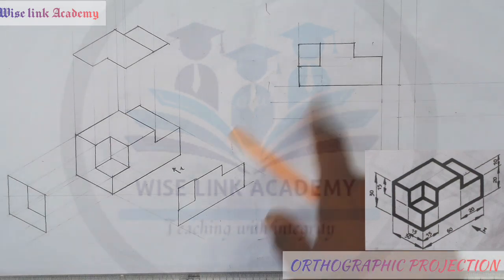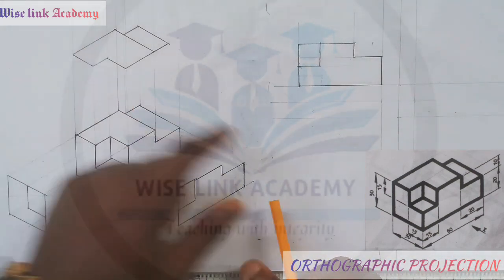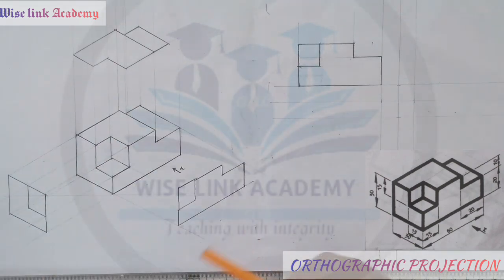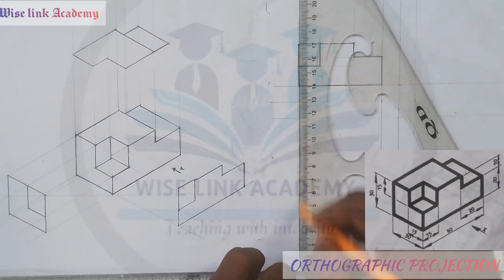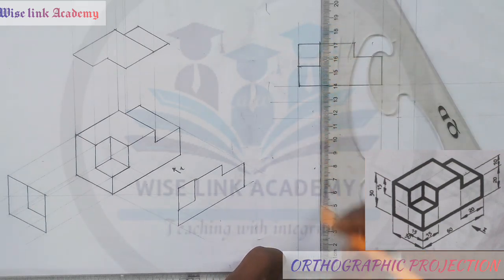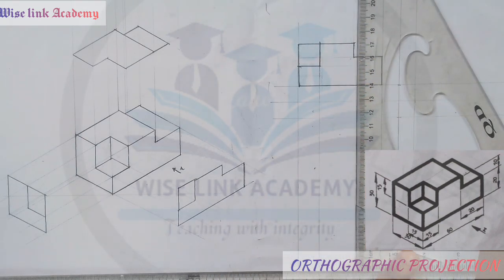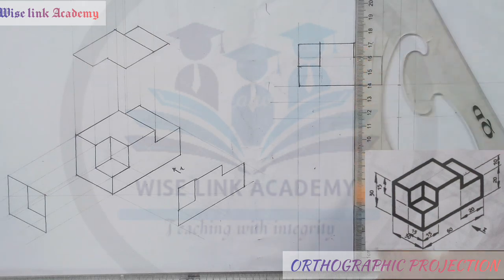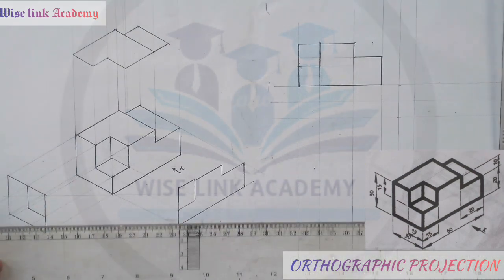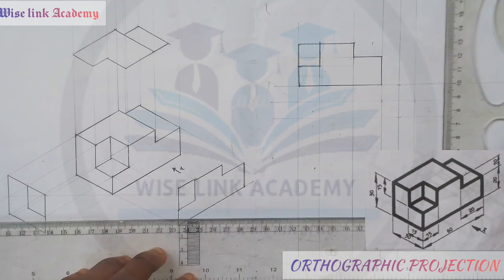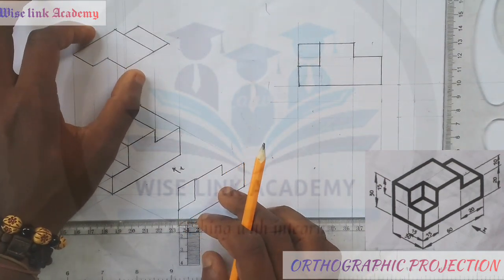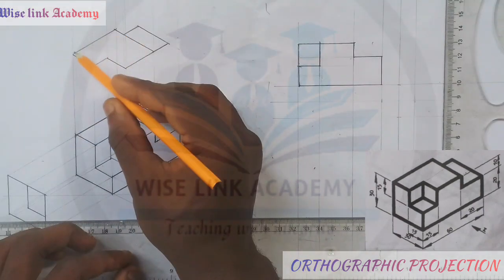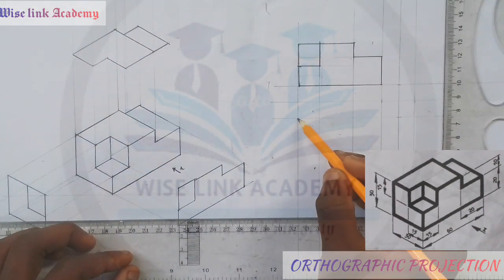Let's discuss the plan. The plan is under the elevation, because I'm told to use first angle projection. So I'll draw this downward, and this one too downward this way. So I have all this, right? I'm told to draw the plan. So how do I start? If you observe closely, I'll tick in from here to here.